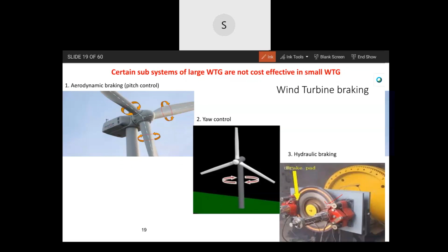People used to wonder, looking at the machine which I have told you initially, that's installed here in Palakkad, in Ahalya, and I had the fortune to be the project leader of that. So its RPM was around 10 to 12 RPM. So looking at it, people used to wonder that such small rotation, can it bring 2000 kilowatt? Yeah, but it is. So the purpose of the brake is, once you're stopping it, then you apply the brake so that it will not turn further. So arresting the shaft, the rotor, that is the purpose.